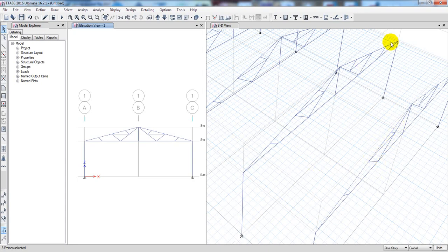So I'll just delete all of that, and we'll provide all points, I mean all joints, as a hinge joint. Okay, or sorry, the pin joint, because you know that this is one of the conditions of a truss. So after that, that will not carry any moment. Okay, and after that I will again come here for design. Right, so when it's done, it's done.